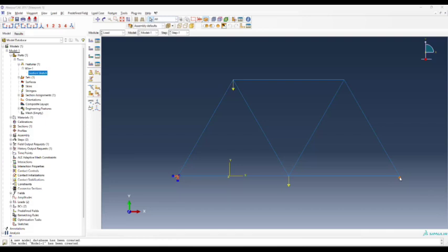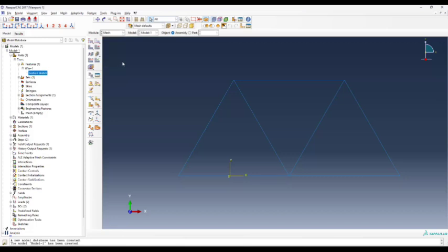All right, any questions, guys? Cool. So let's continue. So now that the loads are done, we can continue to meshing our part. So we're going to go into mesh right here. And we're going to hit the part itself to bring the part as a whole. Now we need to do a special type of mesh to essentially make it behave as a truss.